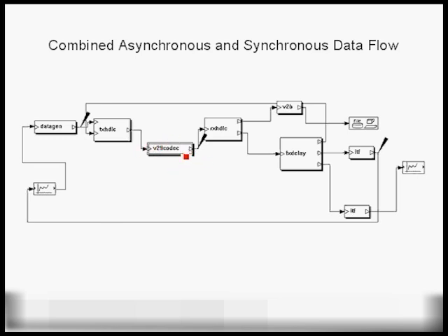This is actually a hierarchical block. We receive the corrupted bits. We go through the receive HDLC, which is again a bit level protocol, and we check the CRC. If the CRC is incorrect, we have a packet error, then we send a request to send back to the data generator. So the data generator will resend the packet, and it goes through the channel again, and if it's received correctly, then we send a positive acknowledgement. Otherwise, we tell it to resend the packet, and this is an ARQ scheme, automatic repeat request scheme.